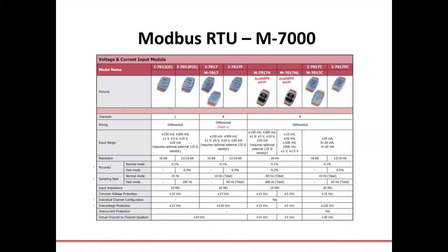Say, for instance, you had some sensors which are 0 to 10 volts, so you can use the plus or minus 10 volt range, and you had others that are 4 to 20 milliamp. Then you'd need to have a module with individual channel configuration. If all of your sensors are common type, you'll save some money and you can get one without that feature.